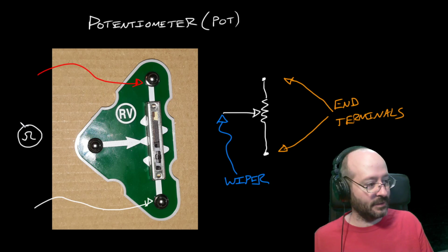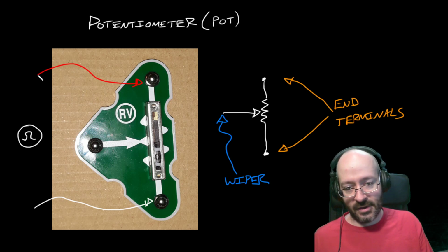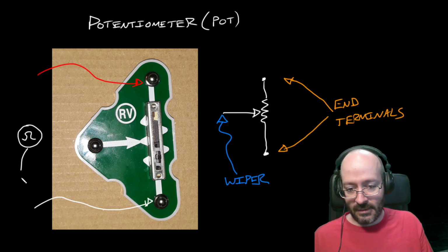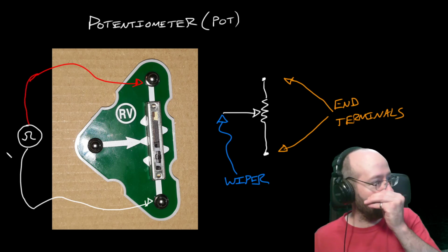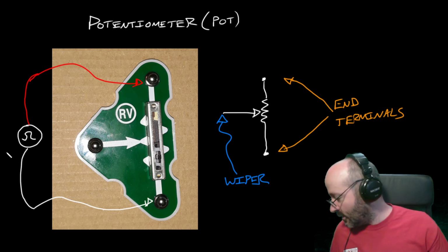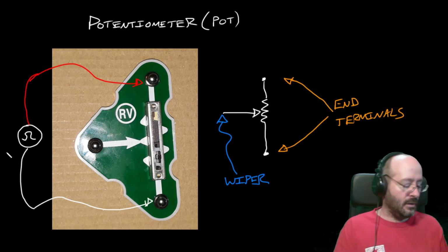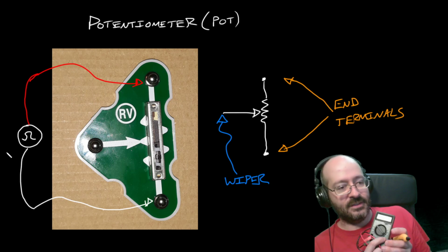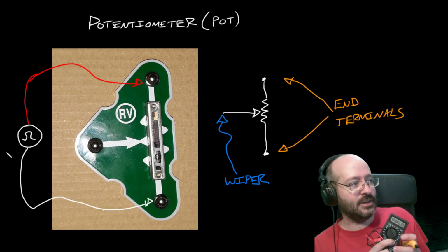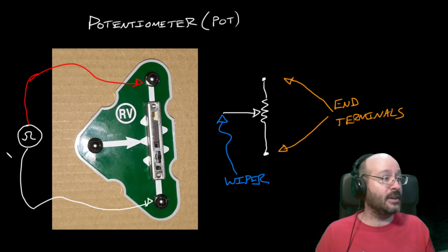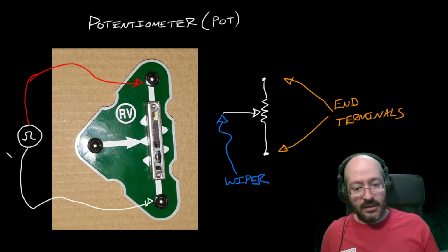So the schematic symbol is going to be a circle with an omega, and you just label it like this. So stick your ohm meter right there: 52.5. And because this is a lower end meter, since the range is 200K, that 52.5 is 52.5 kilo ohms.